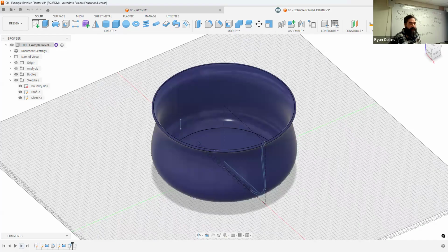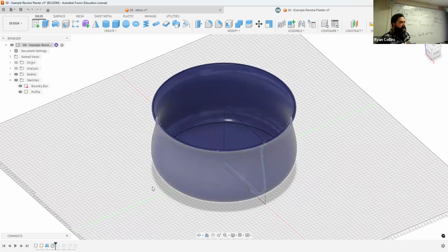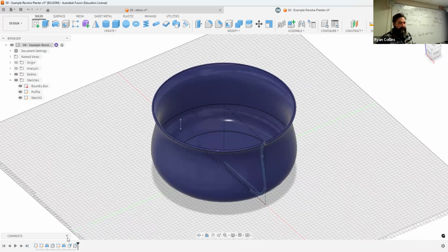And like we were talking about before, you can step back in time on this and say, actually, before I made that alteration, I want to add something and make an alteration here. And you can splice something in, and because it's all parametric modeling, when it snaps back to current, it will recalculate with all this new information. Very convenient way of working. You can add comments in. We'll deal with that stuff later.